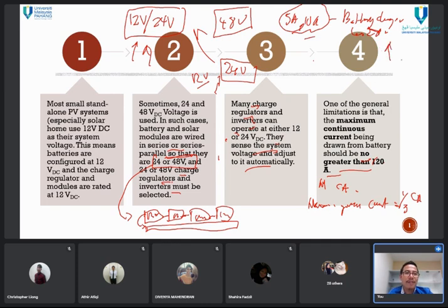And please read, they have the minimum capacity of the battery that can be charged. Dia ada syarat dia. Okay, for lead acid battery, remember, for the sake of the lifetime of the battery, it doesn't mean that fast charging is good. Fast charging sometimes injects the current very fast, and not all of it is properly stored. Even if they have fast charging, it depends on the battery.